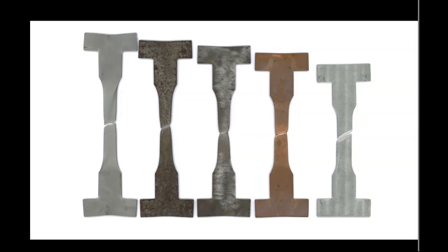So for one material, you will have a line diverging, where the true stress and strain will go up, and the engineering stress and strain will just plateau out. And then another material will have also this tweaked type of a line. Whatever material you have, the stronger material that withstood the higher force will be higher on the graph, and the weaker material will be under that material.